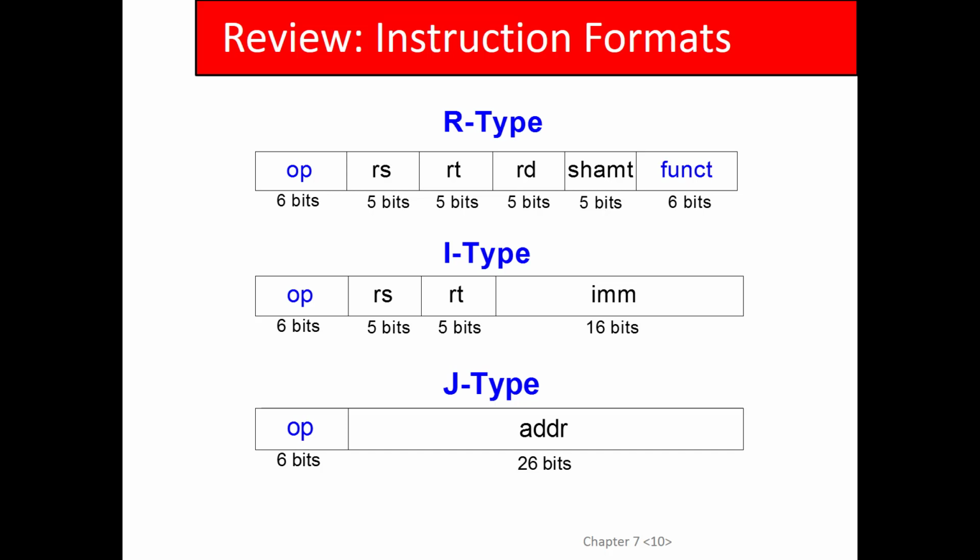So to implement these, you have to design hardware whose inputs are ultimately connected to these fields of each instruction type. So you can kind of see where this is going. The instruction originally comes out of a memory. So you have this thing called a program counter, which is why the counter was in the last chapter.